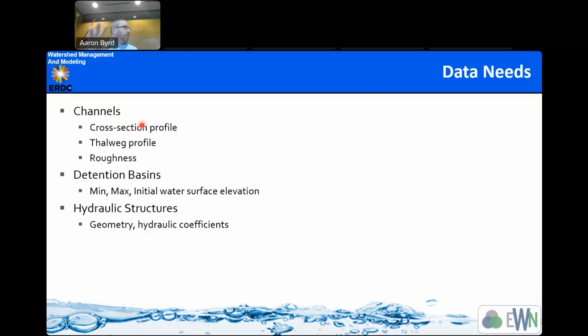Fortunately, I think the USGS has started capturing some of these channel cross sections into a national database. That's recent. So typically, we'll take a day or two and drive around every place the road crosses a stream in the watershed, unless it's private property. We'll survey that cross section in a notebook, or sometimes we get a tape out and go across and measure. That makes a big difference and it's definitely worth doing. Plus, you get to see the watershed you're going to build a model on. Highly recommend actually seeing your watershed.